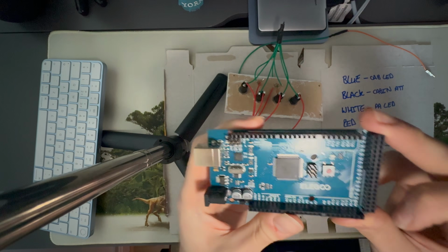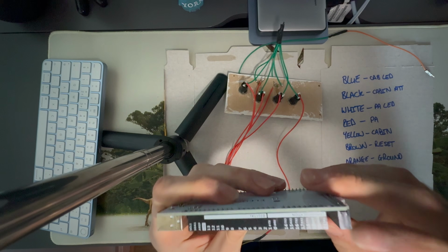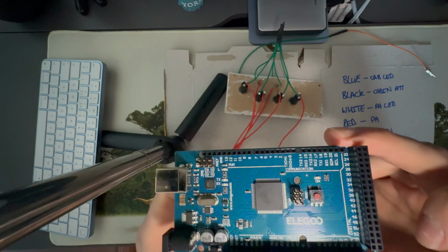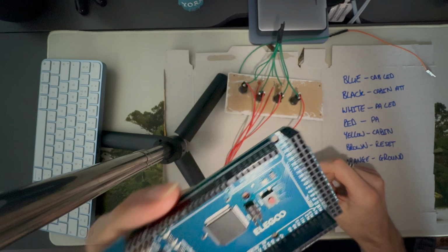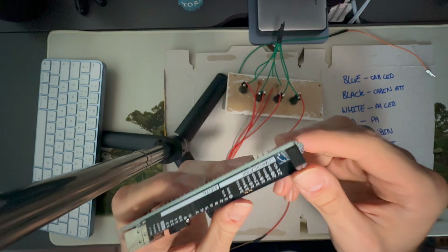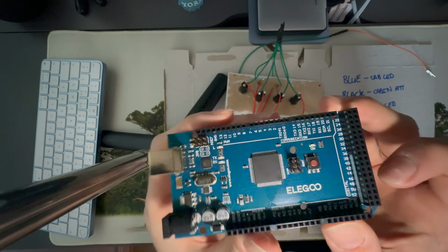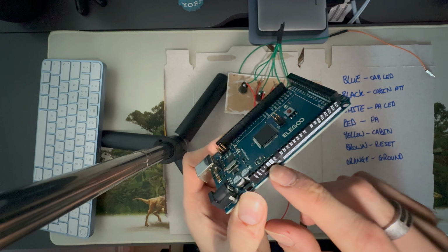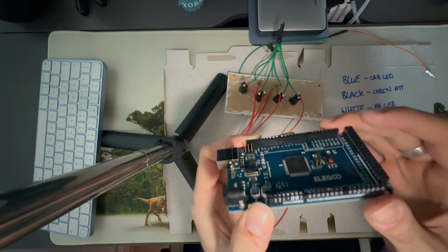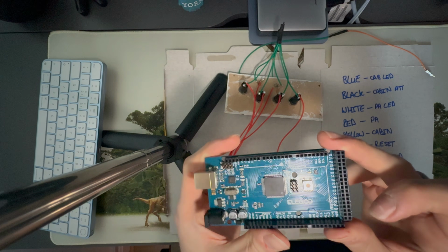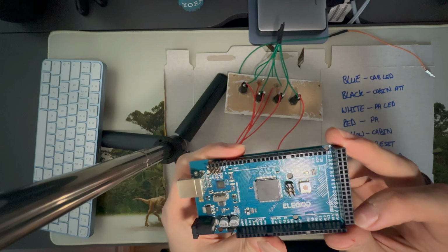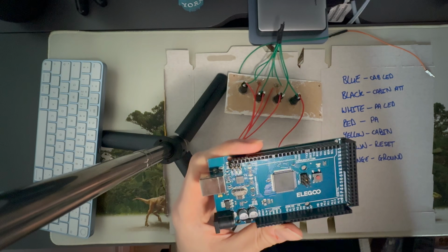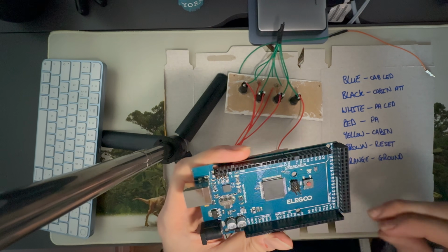And then we've got a number of other utility ports. So we've got the 5 volts. Again, we won't be using them today, but that's more for stuff if you're plugging it into 7-segment displays, like I will be doing with my clock. So I'll make sure to video that so you can see how that all works, because that wires up slightly differently, but the principles are the same. And then the negative pins, the grounds, as well, in various points along the board. So we're going to be using the ground pins and the digital pins today. Doesn't matter what digital pins you use, as long as each component has its own individual pin.